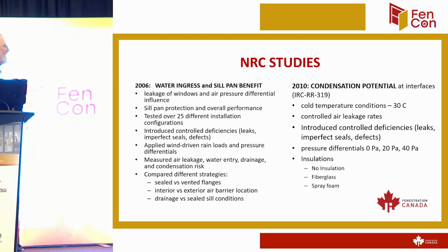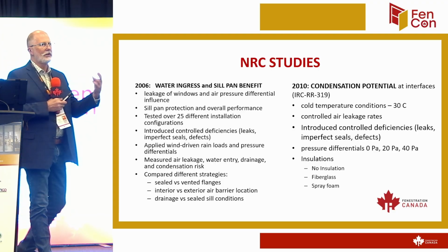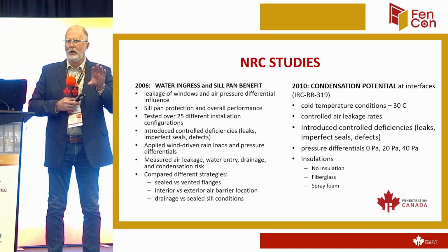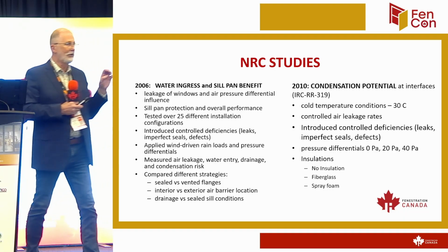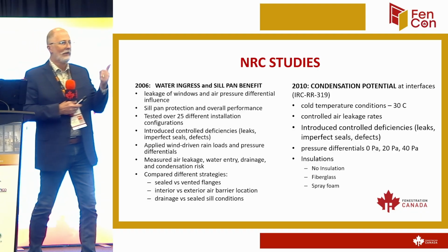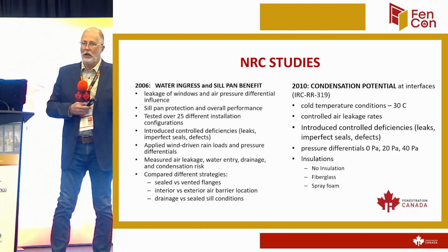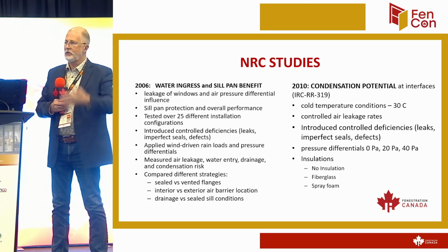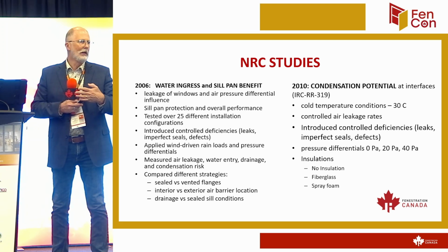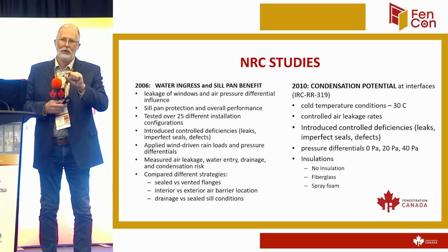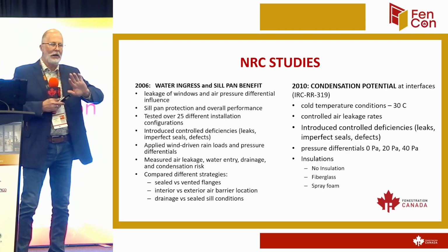They controlled the air leakage rate, like how much. They also put pressure differentials. So not only did they test them with no wind, they also induced pressure differentials of 20 pascals and 40 pascals. And the result was, again, almost no change in the temperature on the inside face of the frame. They were able to get really cold temperatures in the cavity itself, but that didn't affect the frame temperature.